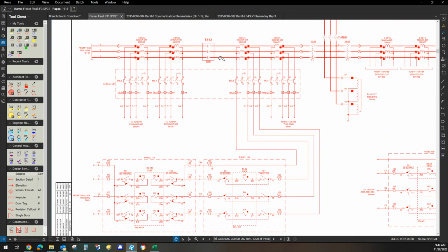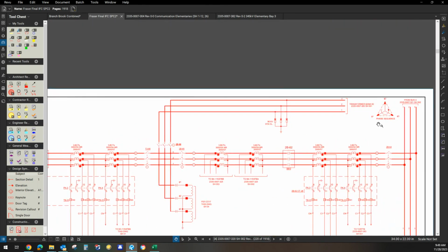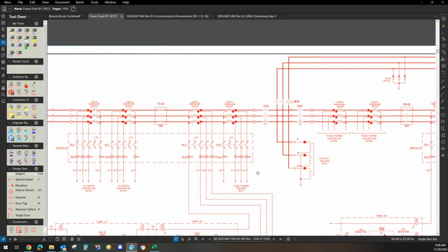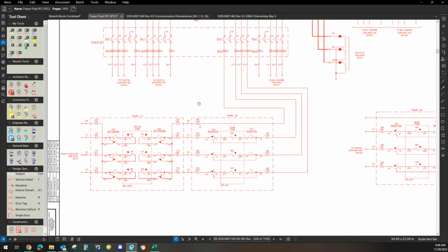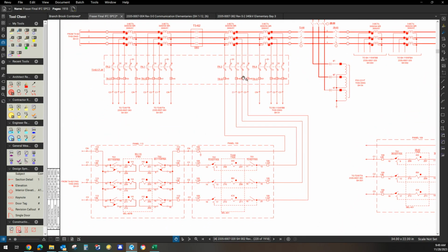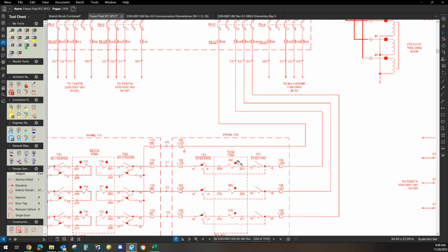this CT circuit leaving breaker T362 on the transformer side. It goes through two sets of relays. So you notice, we'll just pick a phase. We'll pick phase 3. We'll come down. Block DK3, shorting block, terminal board TB22 148, C3 comes down to panel 109. The first relay hits. It's an SEL 451. That's the name of the relay.